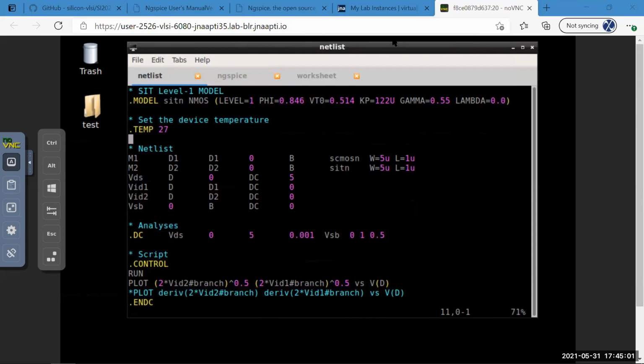So Praveen, this is also modeling the linear region, right? Because these are also the parameters in the linear region. So that's the second part. When we do the IDS versus VDS plus VGS, you'll see that it'll also match the linear region as well. It's not like for the linear region I have to go back, because in the linear region, what do you need? You need KP, you need gamma, you need lambda as well, right? And you need phi. But you have derived those. But if you derive them using the linear region, it is much harder to extract those parameters rather than doing it in the saturation region. Okay. You got it, right?